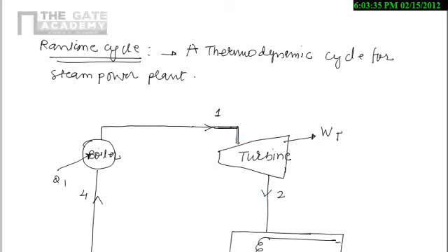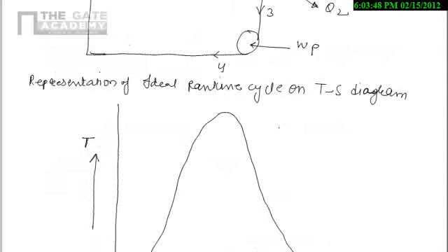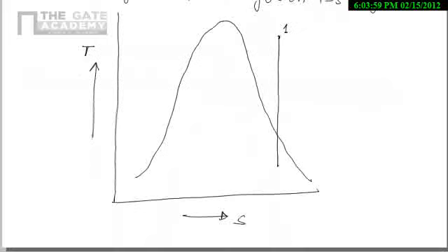That is work done in the turbine. So turbine work done is isentropic expansion, where the entropy is constant. So I will take some isentropic, means the entropy will be constant. Suppose I am here at point 1, and now isentropic expansion means I will go straight vertically because entropy will be constant, and suppose this point is 2. So 1 to 2, this one is the isentropic expansion.